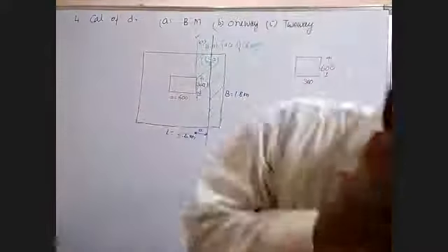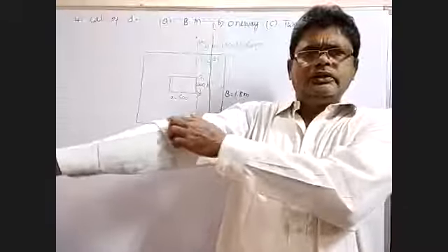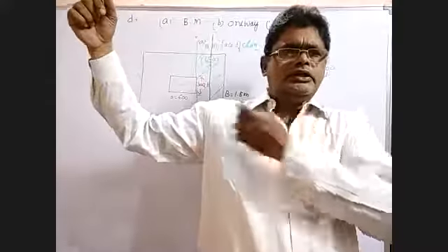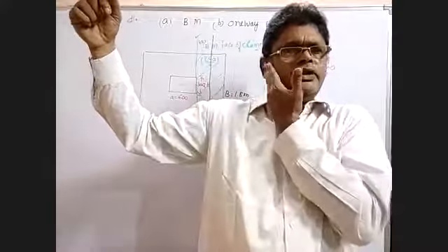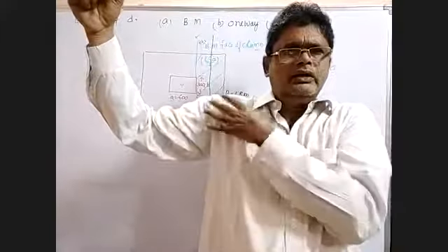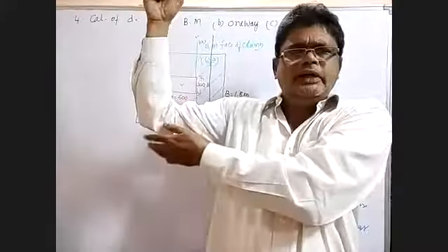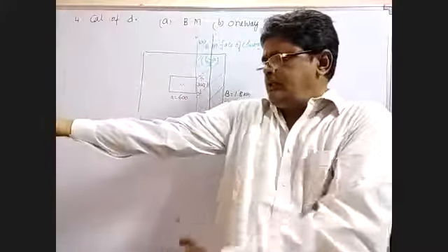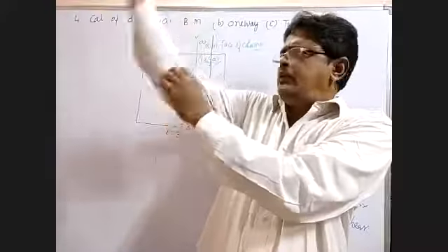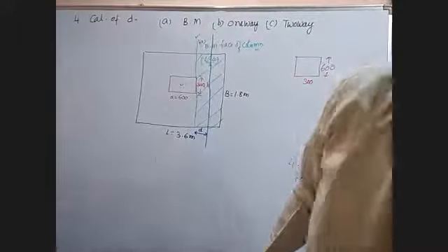Now here, the one-way shear, the failure takes place at this point. So take the elbow here. This distance from the face of this column to the elbow is, let us say, D. So the critical section for one-way shear will develop at the elbow. So there is upward pressure from the bottom, and because of the pressure it lifts and failure comes here. So that is the one-way shear here.